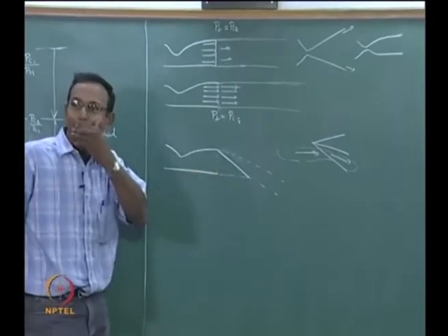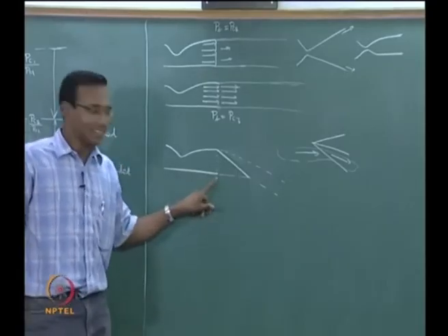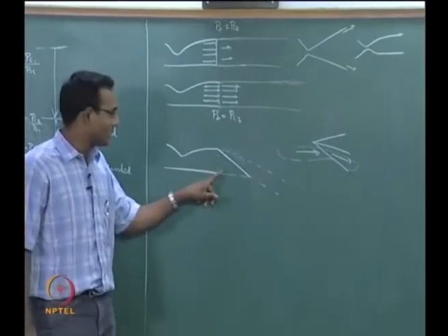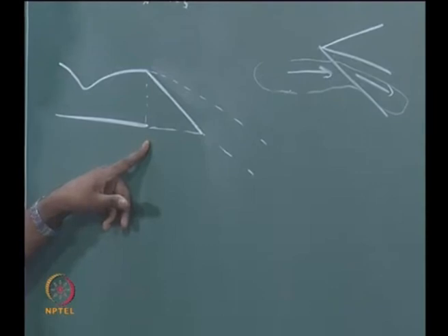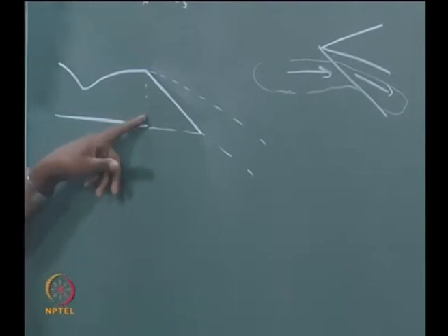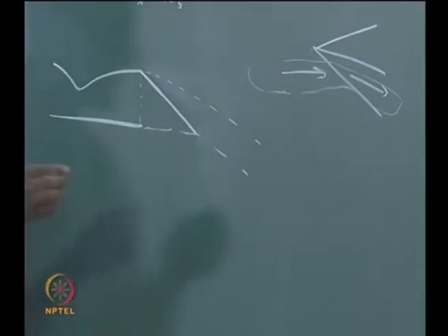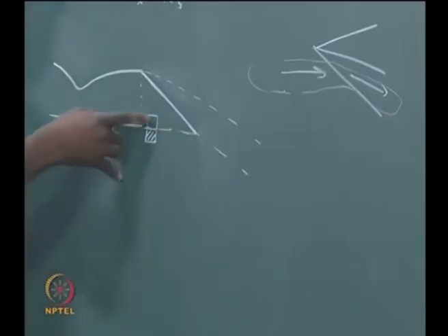There is some other mistake here. What is the mistake? At the bottom line, the pressure here is the same as the pressure here. There is no shock here, which means the pressure here is the same as the exit pressure, but the outside world we said is PB greater than exit pressure. That is why it is an over expanded jet, right? It is expanded too much compared to this, which means this pressure is lower, which means currently I have a layer where the pressure here is higher than, I will draw with hatch, the pressure here, that is lower pressure, this is higher pressure.